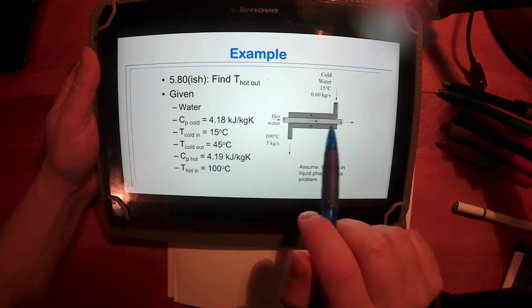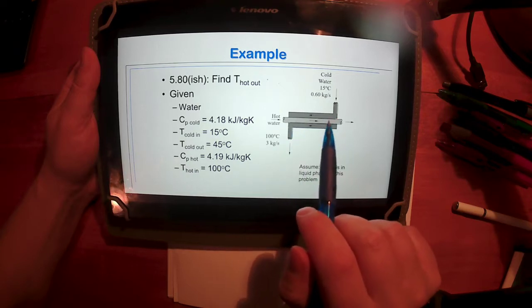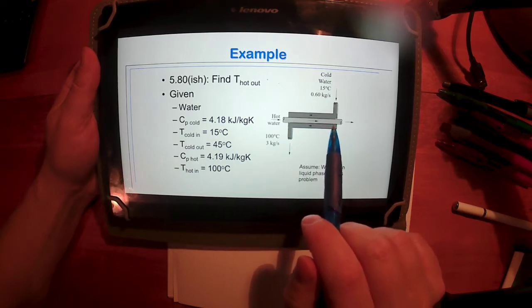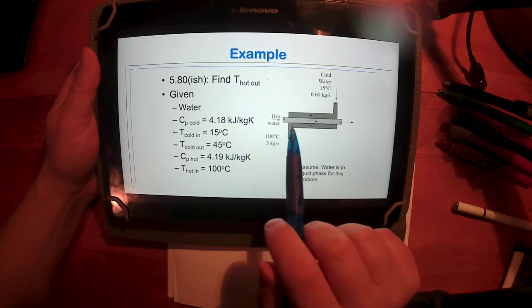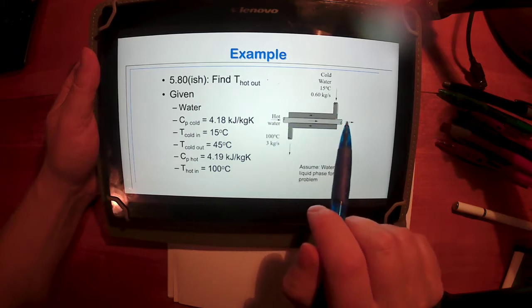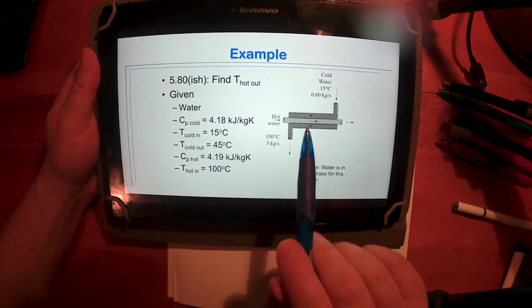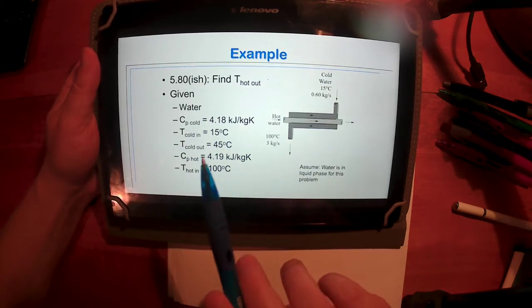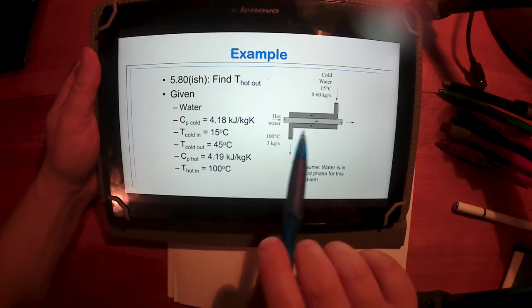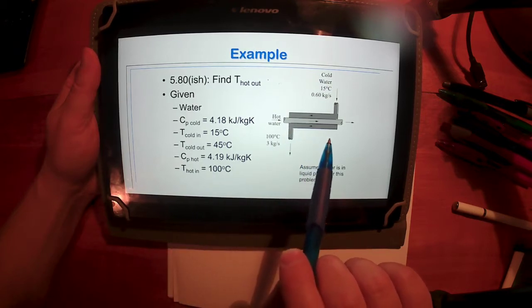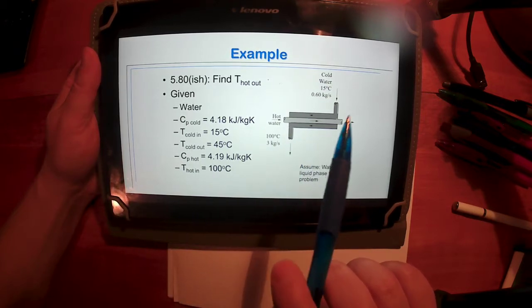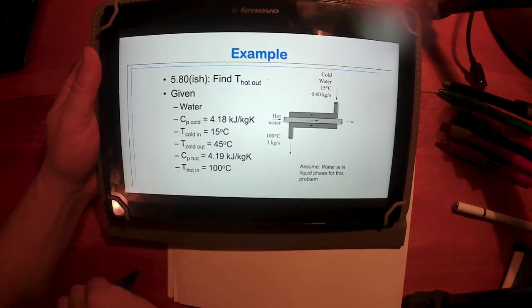Double pipe just simply means you've got one pipe inside of another one, and counterflow means that the fluid is flowing in opposite directions. If the hot water is flowing left to right, the cold water is flowing right to left, as shown in the diagram. So double pipe just means that this pipe is inside the other one, and we're just seeing a cross section of it. Again, the thin wall just means it's a very, very fast transfer of heat between the two systems.